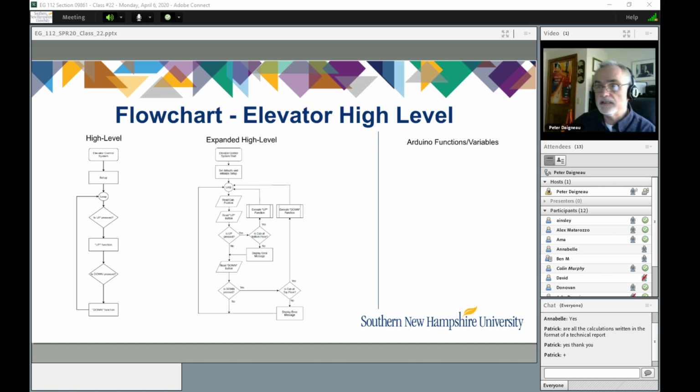All right. So basically, if you had to determine where the cab was, you would read the cab position, and then you would monitor the up button. And if the up button was pressed, you'd then make a determination: is the cab at the bottom floor? If it was, you'd execute and then reloop. If it wasn't, you'd give an error message and then go to read the down button. Because if it's not at the bottom floor, it's at the upper floor, and the chances are the button that's going to be pushed that you're going to want to process is the down button.